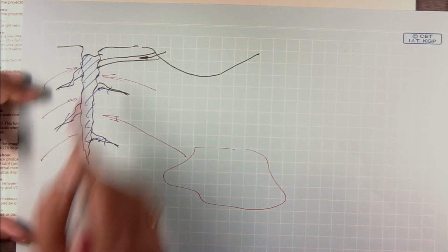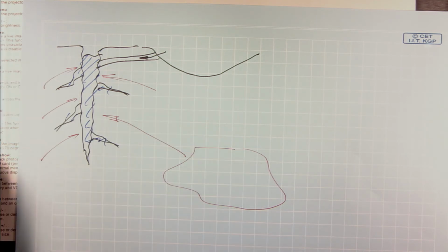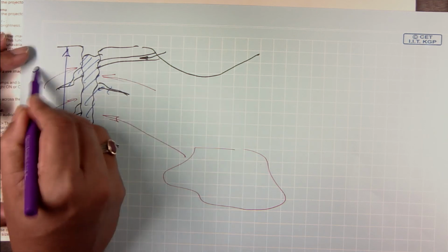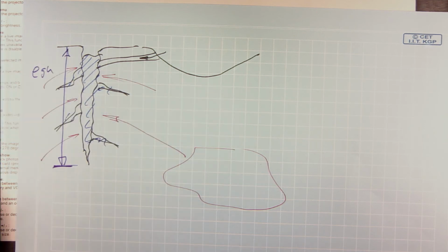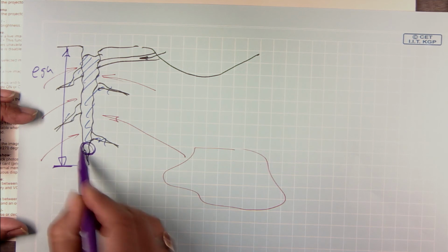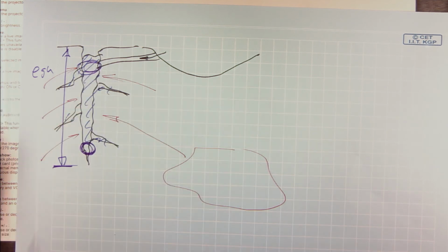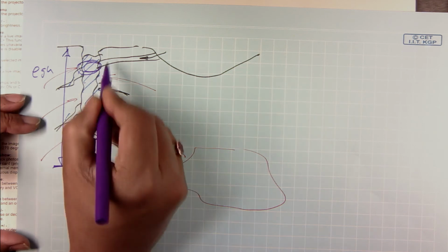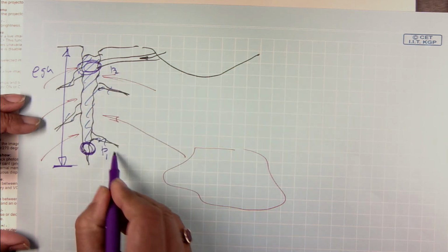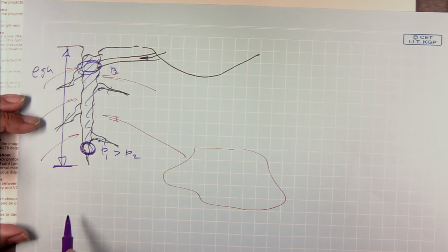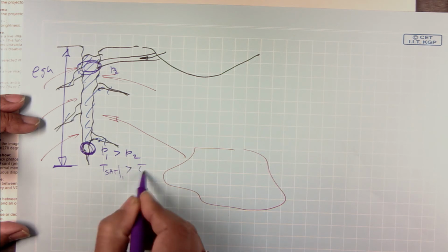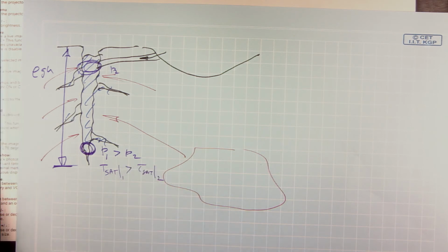But this one is going pretty deep, so you have a big variation in pressure, because you have a rho g h, right, of pressure at the bottom over here. So, the pressure here is actually much higher than the pressure here, which means, if I look at P1 here and P2 here, your P1 is much greater than P2. So, therefore, the T_sat here is much greater than the saturation temperature here.